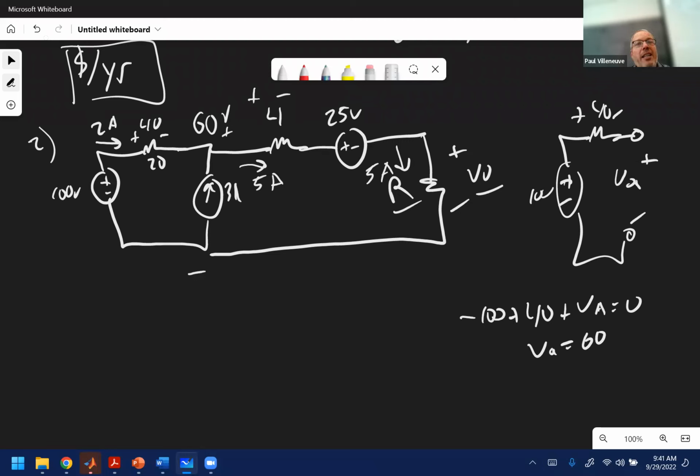Partly the cold cranking amps, it's a little more than that, but that's like the general capacity of a battery to be able to start something, because you need a lot of power. Your starter is the one that absorbs the most amount of power. So when you hit your starter, it pulls in massive amounts of current. And if you can't pull in a massive amount of current, it might not have enough oomph to turn it over. But there's also an amp hour rating on the battery, which is, okay, what if you're going to park your car for an hour or two and you're going to listen to music or something like that? That's a factor as well.